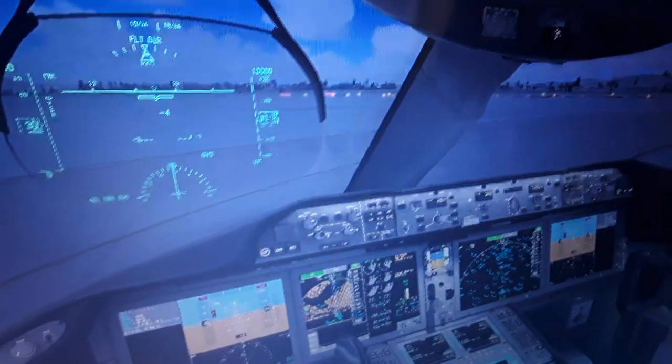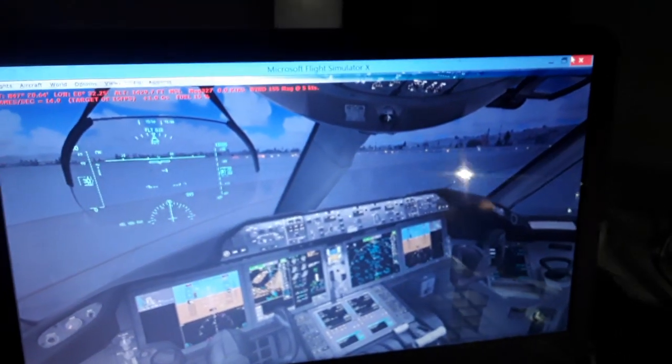We're going to climb to cruise level like 29, 30,000 feet above sea level. We're going to cross through some waypoints and then descend, make a right turn, then descend back to the elevation of the airport. We're going to align with the magnetic heading of the runway for approach and landing with the STAR terminal arrival waypoints and fixes, and also with the LSZH localizer that I told you. We're going to use the flaps at 5, 30 degrees. The landing gear extended at an airspeed of about 160, 170 knots, like 270 kilometers an hour, and pitch attitude 9 degrees or less. So we're going to use the LSZH localizer, the instrument landing system of the airport. And we're going to have a complete flight plan.